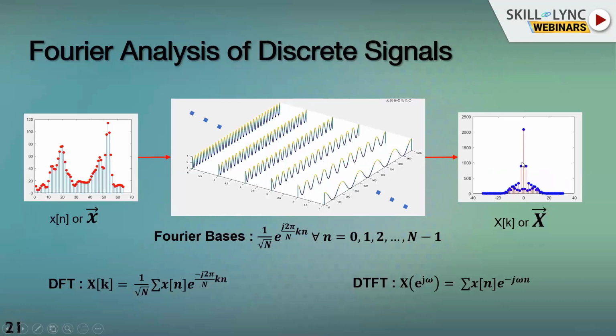We can see that the information revealed by taking the DFT is of a different kind. Here we have time domain information, and we can see how the signal varies in time. Once we take the DFT, frequency domain information is revealed, and we can see what kinds of frequencies are present in the signal. From the picture, there are more low frequency components than high frequency components. So this is particularly a low pass signal, because we have very high energies in the low frequency components of this signal.